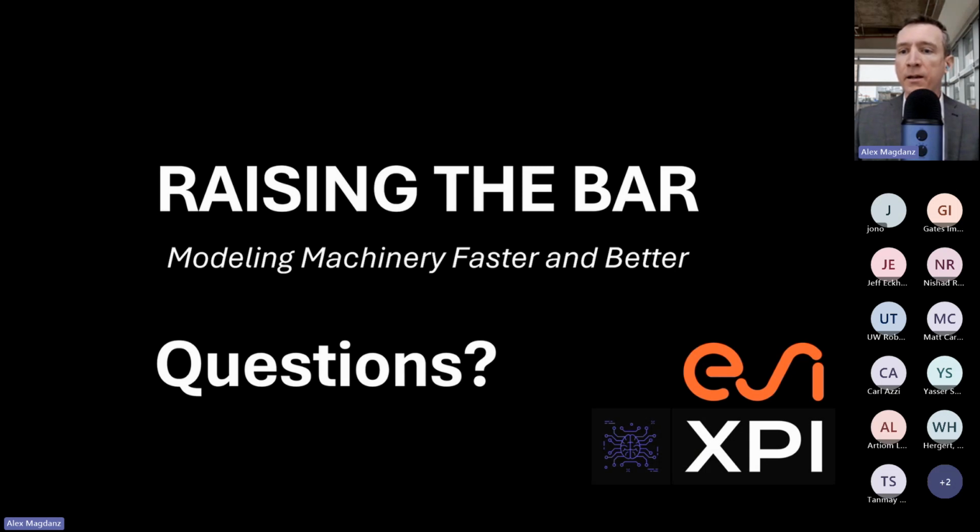Then we have another question: how does SimulationX solve closed-loop chain problems in an inverse dynamic simulation? That's quite a specific question. We'd have to take a look at the problem you're trying to solve. But in general, this is equations-based modeling, meaning that you can set the boundary conditions that you're aware of, and it will solve for the others. It's not signal-based modeling that only has a single calculation direction.